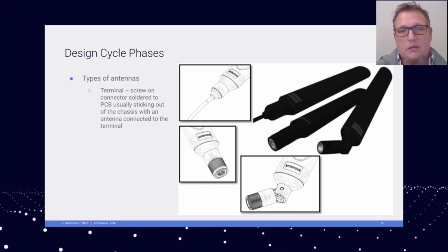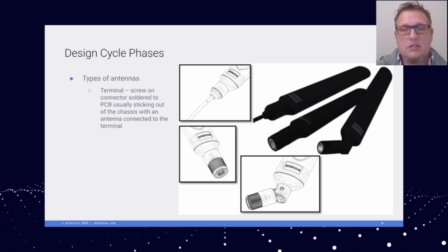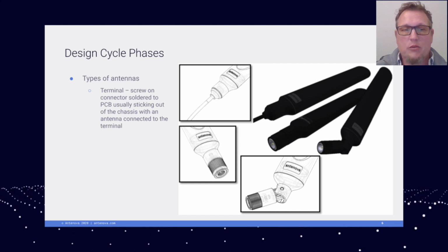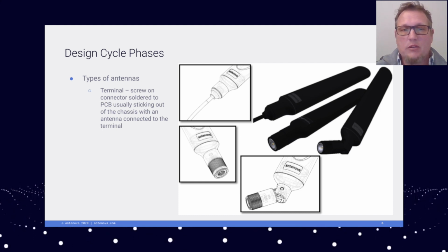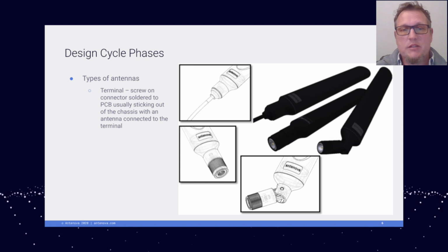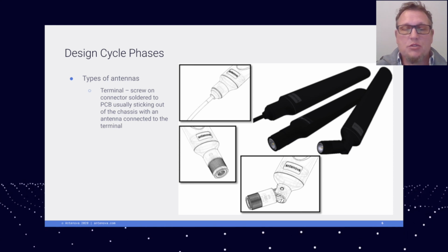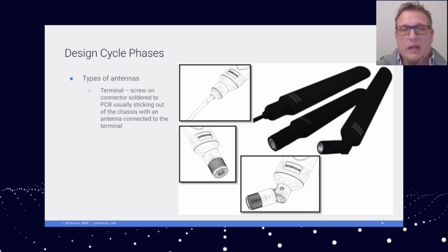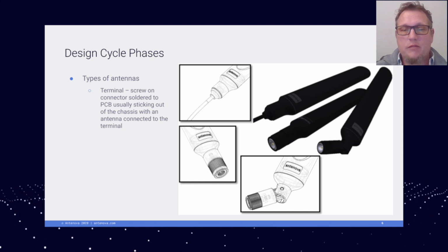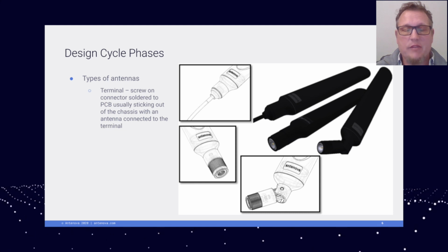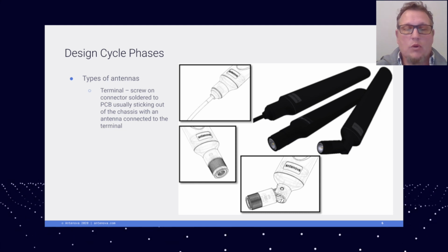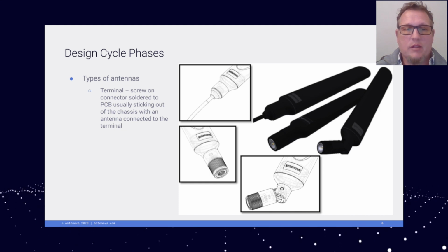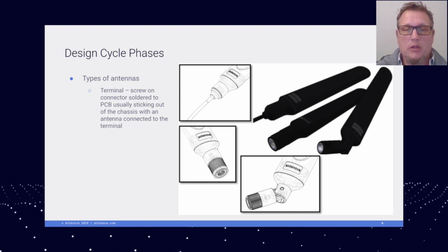So the efficiency on these antennas tend to be a lot better because you can get them away from your device, the ground plane, or any other metal parts of your device that tend to cause issues with the antenna performance. They are also not ground plane reliant because they have a balanced antenna structure inside of them, and therefore you can mount them pretty much anywhere on your device without having them be detuned by a smaller ground plane.